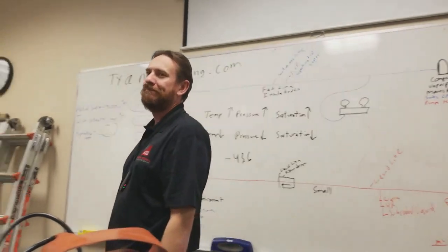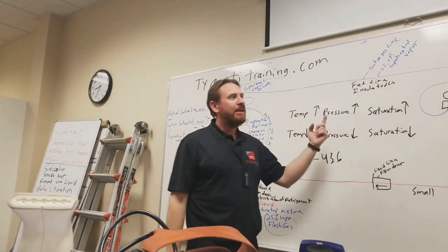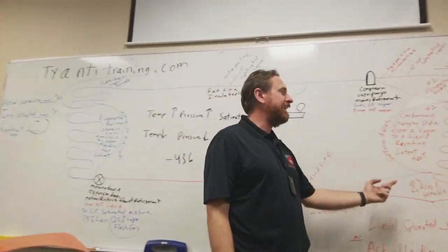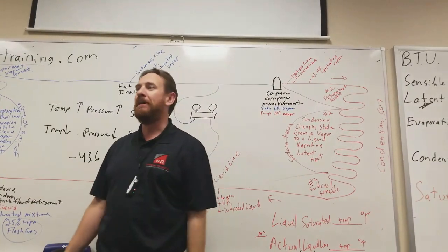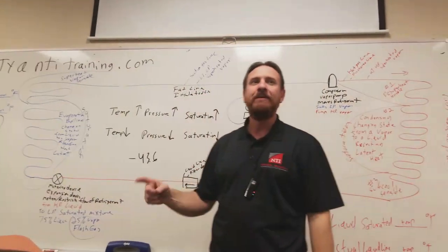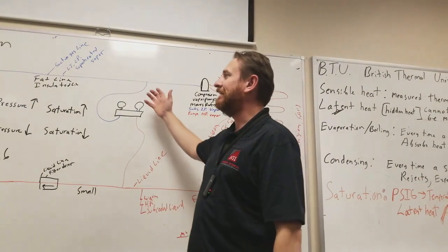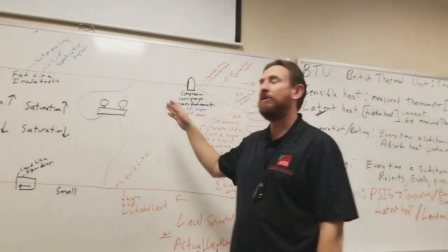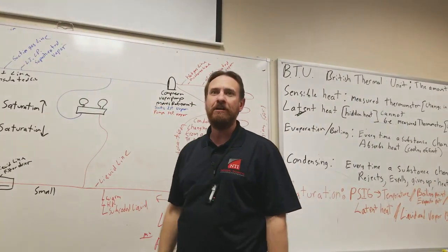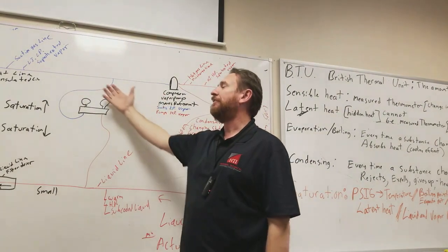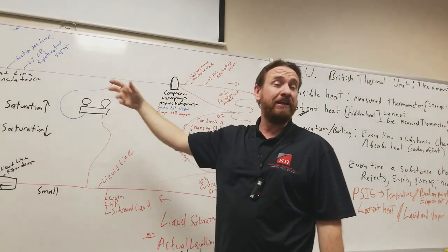Right? So, same thing. There should not be oxygen inside of here. Yes, it could leak. Yes, you could have a problem. But if you do it right, there's not going to be a problem. The most dangerous part about propane is when I take the refrigerant out, take the propane out, and I need to work on this. I have to braze these lines up. When I braze these lines, now there's oxygen, now there's heat, now there's a fire going. It could be a problem.